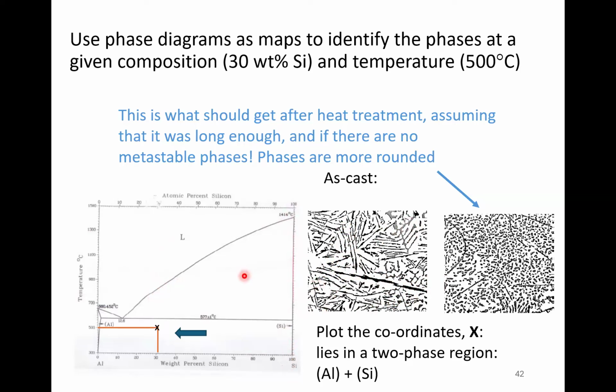So they can do two things. They can either hold it at temperature, in which case you get a structure more like that, because holding at temperature below the melting point, below the eutectic, this has now got high energy because it's got high surface energy. So the system, the metal itself, will want to reduce that surface energy and will round off these silicon needles to make globules, and that gives you much better properties.